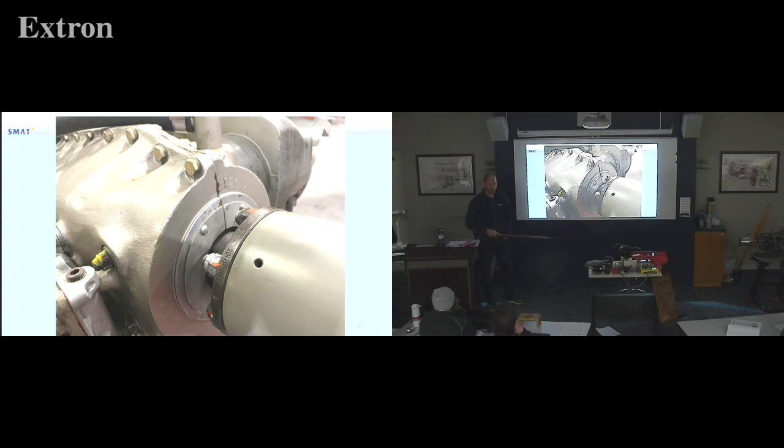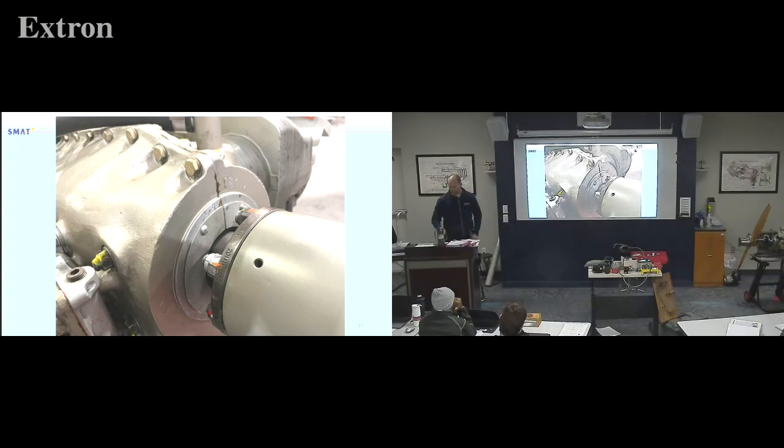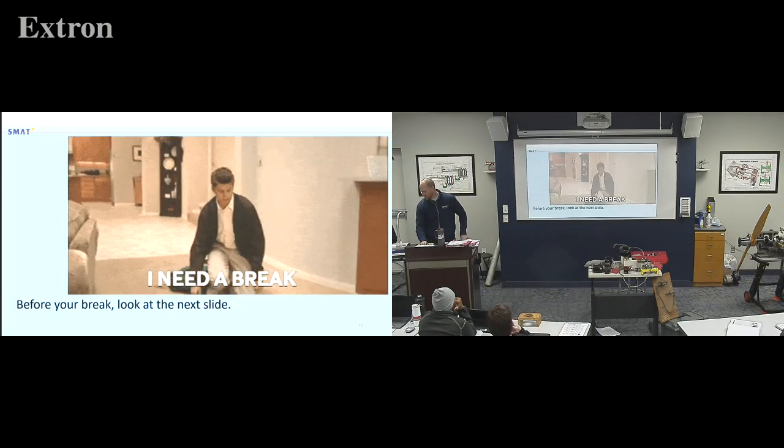No, it's a bottom feeder. The push rods for the valves are on the bottom. You're going to line this line up with the seam on the bottom of the engine, which on an aircraft that's functioning, usually you can't see that because there's a cowl in the way, right? But on some of your engines, or if you're timing it, you'll be able to see that. And guess what? Because it's not the top dog, that number 1 cylinder, it's afraid of the prop. So number 1 cylinder on a Continental is as far away from the prop as it can get. So if you remember those little tricks and jingles, you'll do well.